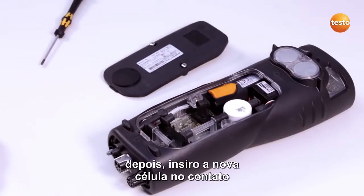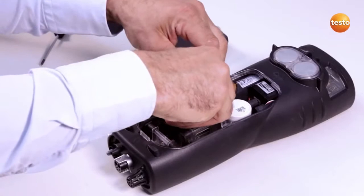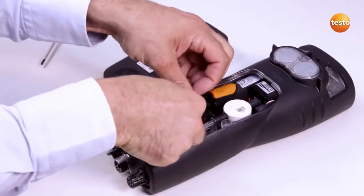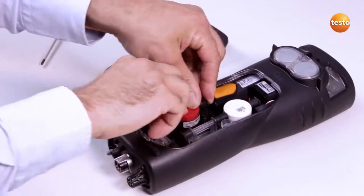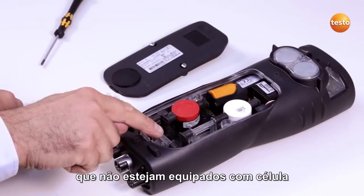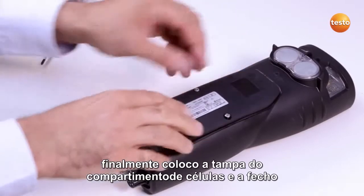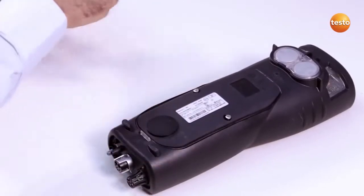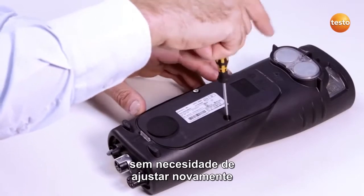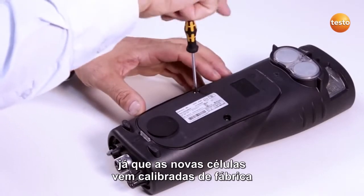Then I insert the new sensor into the slot and connect the sensor to the hose connections. A slot bridge must be inserted in slots which are not equipped with the sensor. Finally, I put the cover of the sensor compartment back on and close it. After replacing the sensor, another measurement can be carried out straight away without adjusting the sensors again using test gas, because the sensors are factory calibrated.